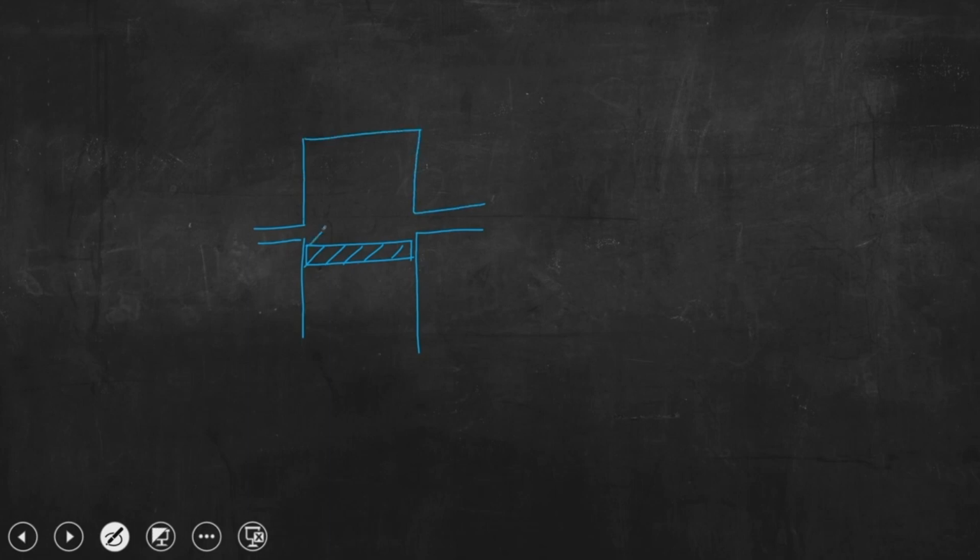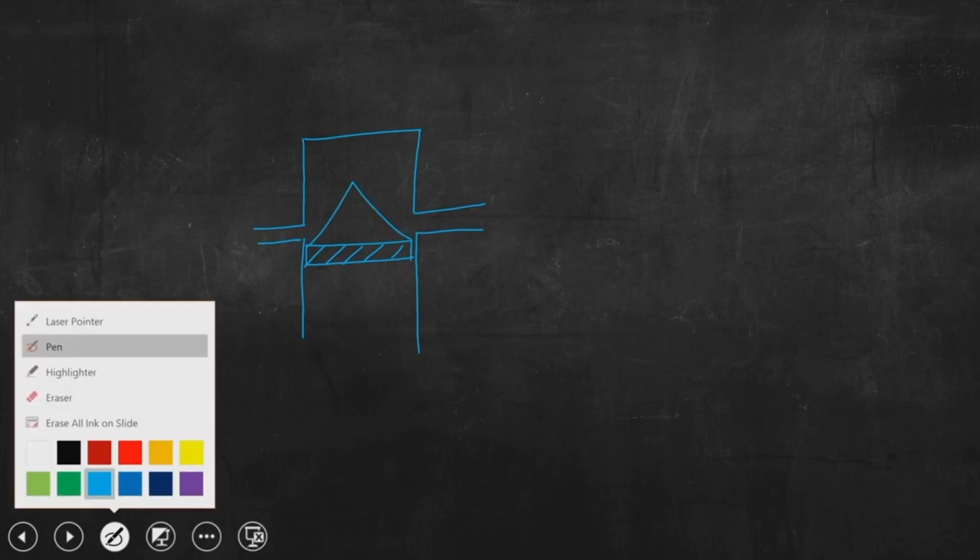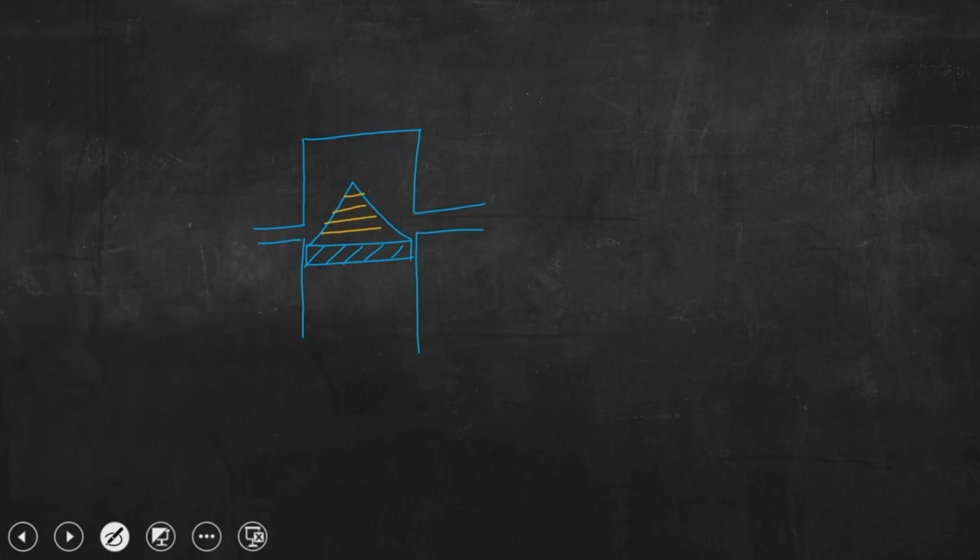If that is the engine, this is the piston, and it is shaped like this. This is known as crowning. This special geometrical arrangement is done so that when fresh air-fuel mixture is coming, if it is the SI engine, or fresh air for the CI engine, it will be allowed to move in this direction. So, we can understand this particular geometrical configuration will allow the combustion gases in the remote corner to go out from the engine cylinder.